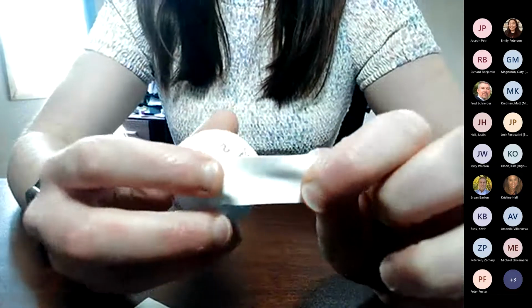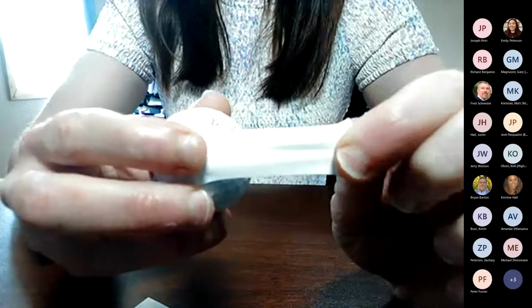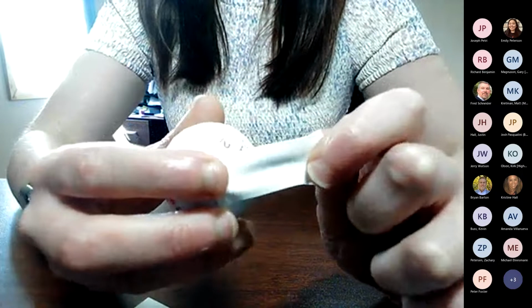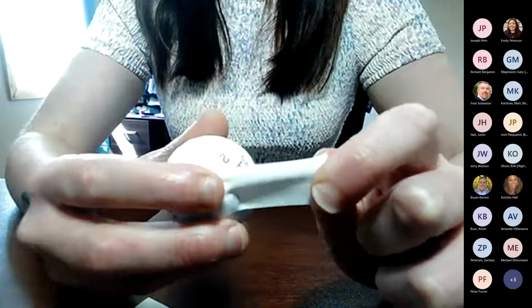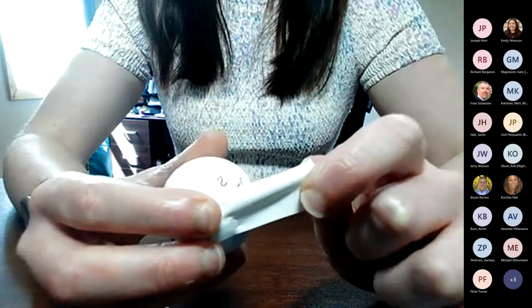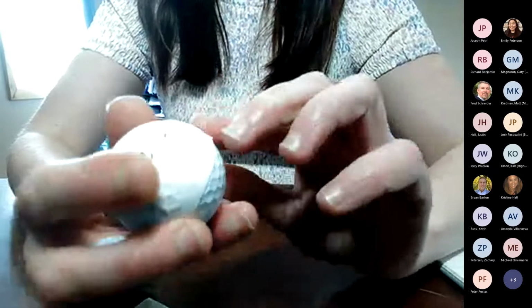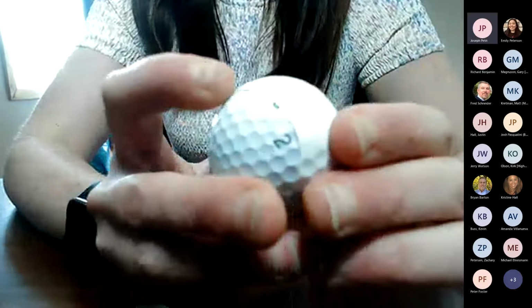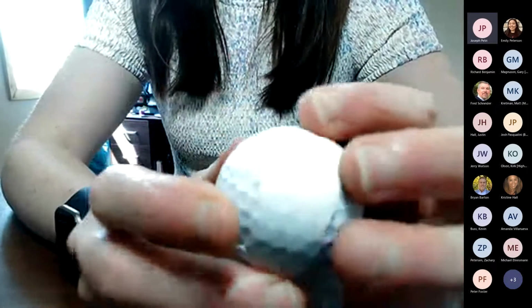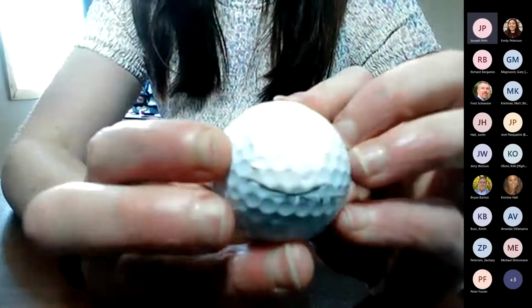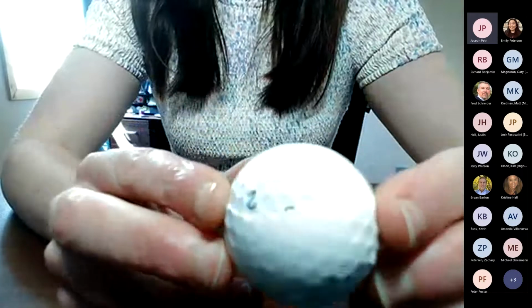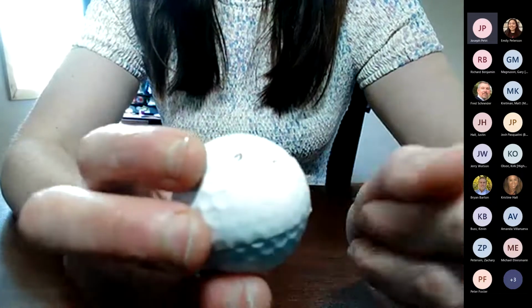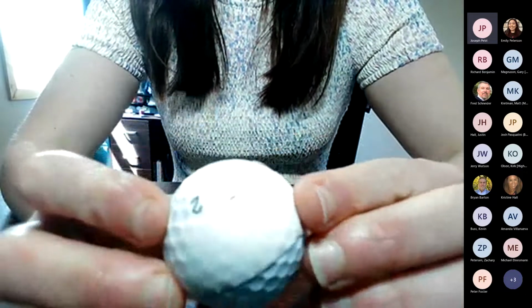What's really unique about this is it's got some viscoelastic properties. So you see how I can pull it and it goes back. That's good for an application on something that's moving, like automotive or aerospace, where it's going to be really important. It also helps with the coefficient of thermal expansion between different substrates, and its ability to absorb a little bit of that shock and vibration and CTE is a great benefit for this tape.